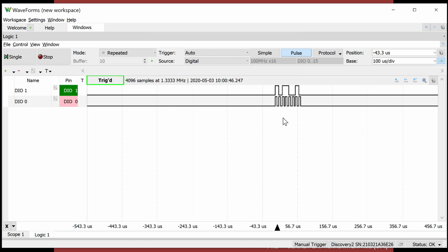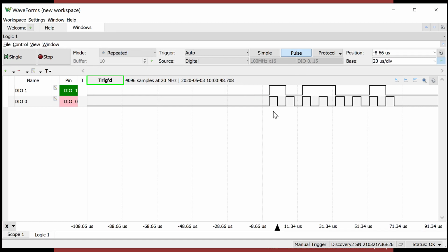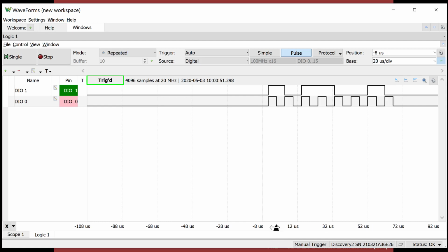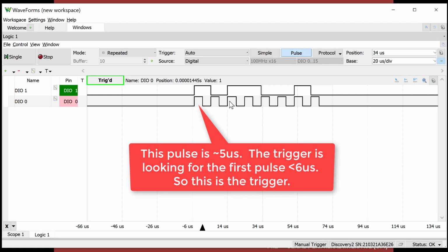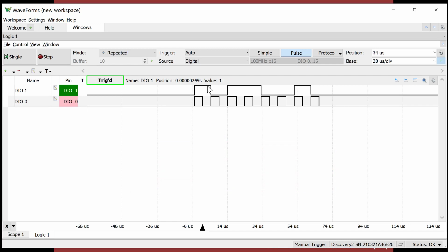Now let me zoom in now that I see what's happening here. And look at this. Lo and behold, again, we are able to see the information. So here's SCLK, 1, 2, 3, 4, 5, 6, 7, 8. And then there's the data. Notice that the data now is not an analog waveform, it's a digital waveform. One of the things you can do with a logic analyzer is use the bus features, which will interpret the data and decode it for you. In this situation, all the decoding consists of just flipping LSB and MSB, but it can actually tell us the hex value of it.